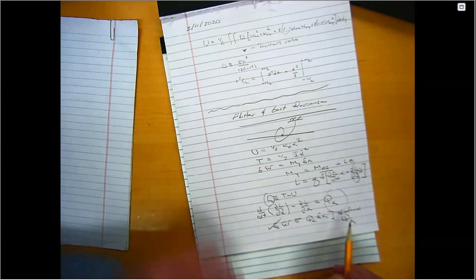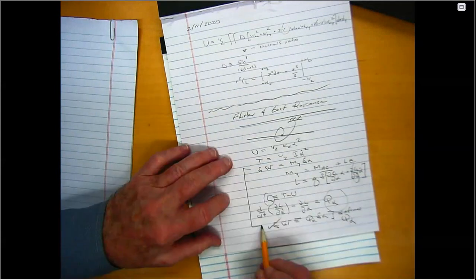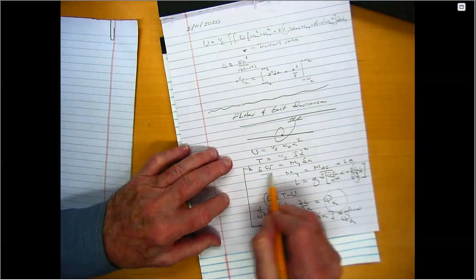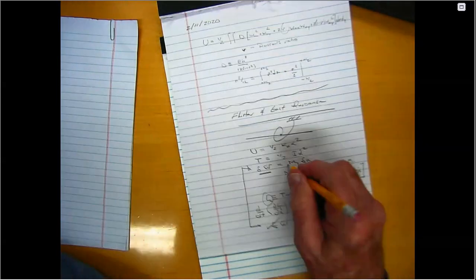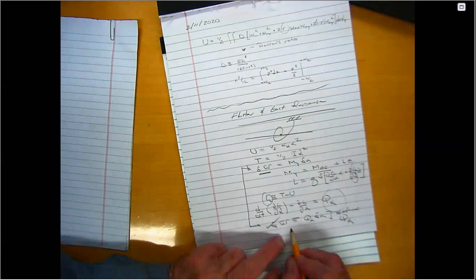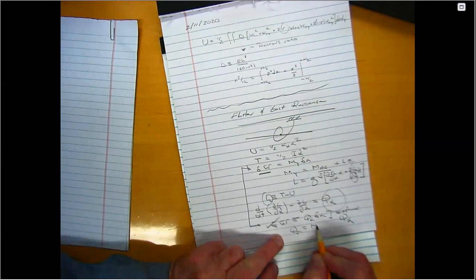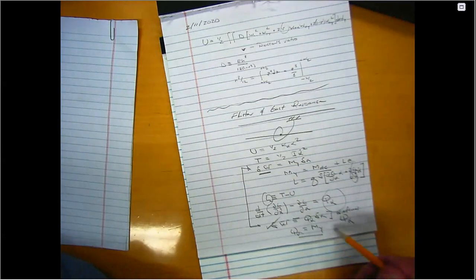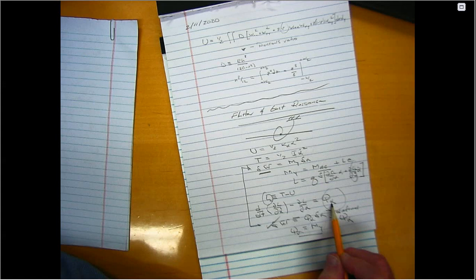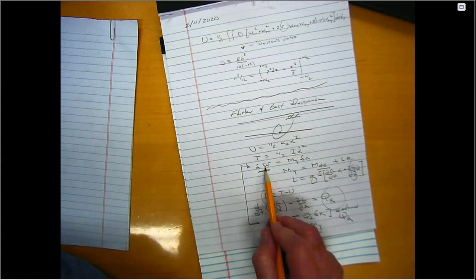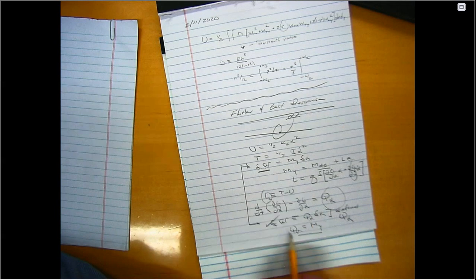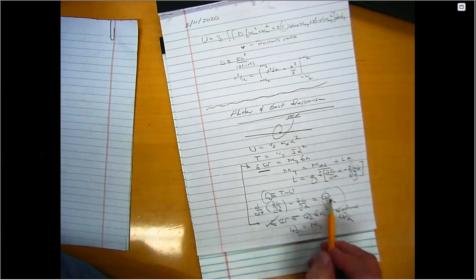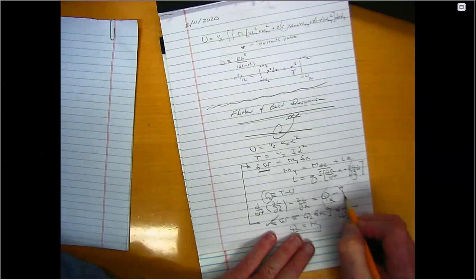But then if I look back at this expression, which came from physical reasoning, and I compare these two, then I conclude that Q sub alpha must be equal to M sub y in this case. In other cases, the relationship will be a little more elaborate. But that's how I find the Q sub alpha in Lagrange's equation. I construct a physically and mathematically valid expression for virtual work, and then identify the coefficient as Q sub alpha. And this is usually called a generalized force.